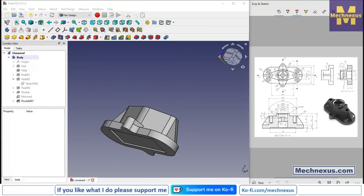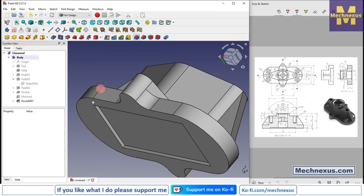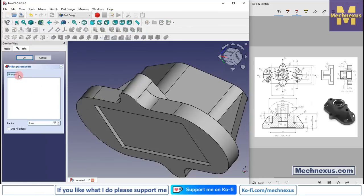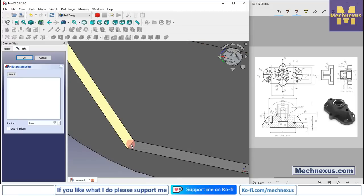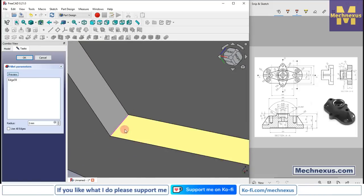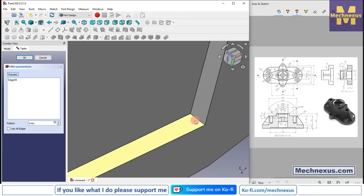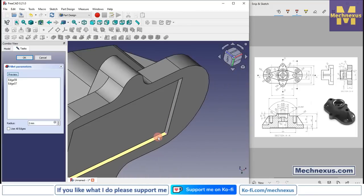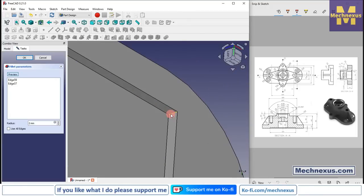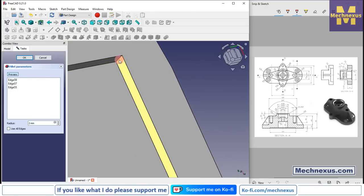Now we will provide the fillet. So select the fillet tool, and here we will provide the fillet of 2 mm, and we will select these corners. Select this corner. So once it is selected, it shows in a pink color, and now we will select this corner, this corner, this corner,